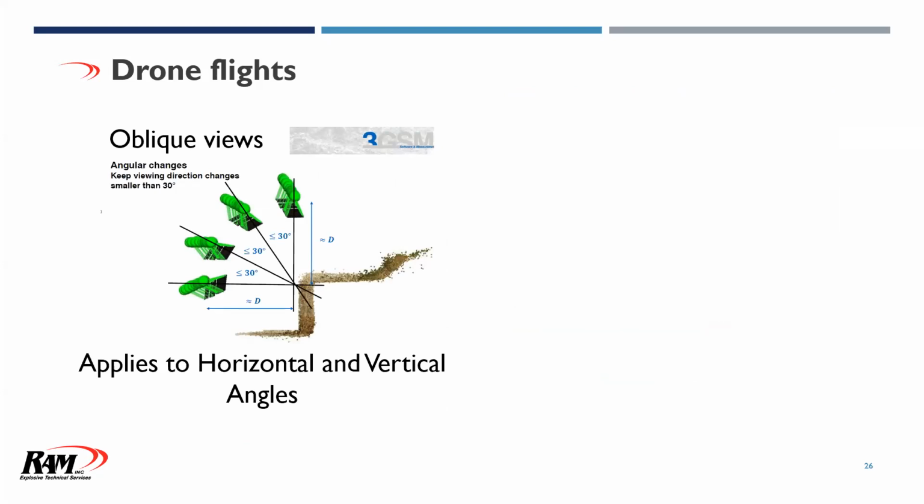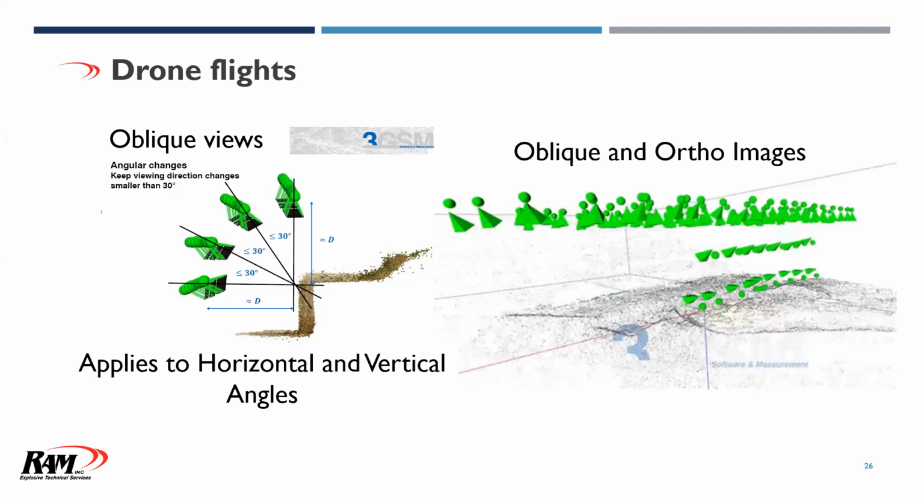Depending on the height, depending on the area, that would determine how many flights you would take across there to capture it. But it could be that you're going to have to get down right directly in front of the face and fly parallel to it, taking your images perpendicular to that to be able to get good coverage across that face like we see here.